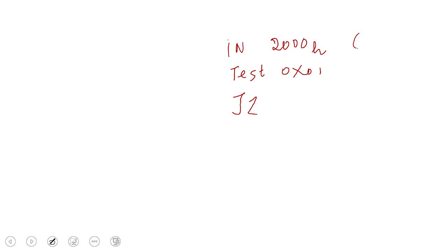It was mentioned that the test takes 8T cycles and the sum 0 takes 4T cycles. If the sum 0 condition is true, we go to the next step and don't go back, so it takes 4T cycles. If it is false, it takes 12T cycles. Similar code was in the lecture.